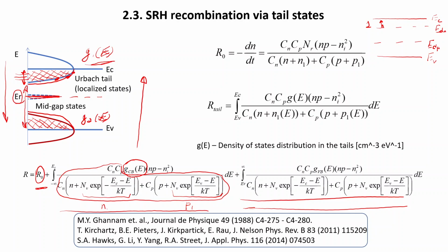In this region, let's say it's region 1, all localized energy levels which are located in region 1 will work as trap centers. It means they will trap charge carriers and keep them at this energy level without recombination, and over some time, because of thermal activation, they will just detrap. So we have a trapping event and then a detrapping event. From your point of view, will the presence of such energy levels affect the concentration of non-equilibrium charge carriers in the semiconductor or not?